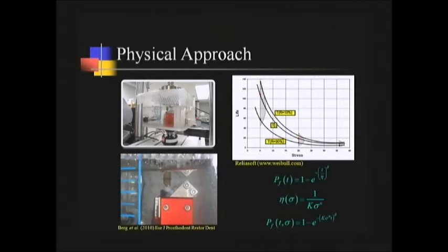And those of you who are already familiar with Weibull statistics, I came about a year and a half ago and talked to you about Weibull statistics. And so if some of you were present then or doing research in the area, you will recognize this equation. This equation is the Weibull strength equation, except it's been modified a little bit to account for lifetimes instead of fast fracture strength. The beta up here is the Weibull modulus. Sometimes we use M instead of beta to stand for Weibull modulus. That means the same thing.